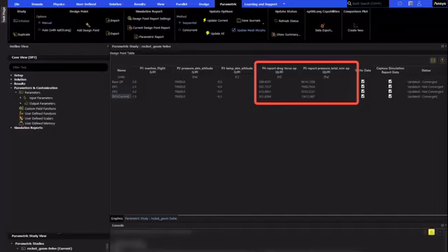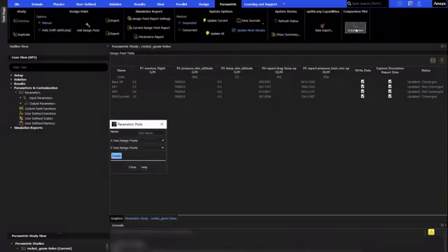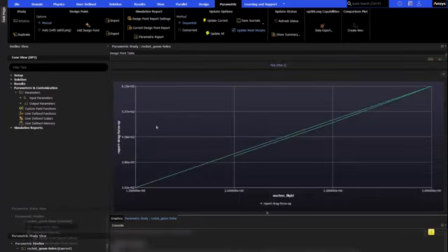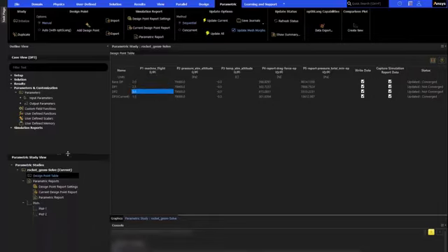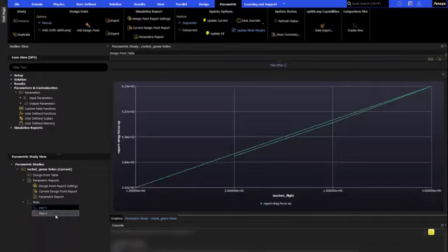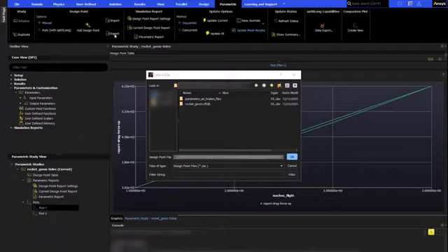To view graphically, you can also create a comparison plot for the desired variables. Here, we'll plot the Mach number against the rocket drag force. Here, we see a doubling back of the plot line because the data is plotted sequentially for the design points run. However, the design point table data can be exported into CSV format and be manipulated further outside of Fluent by selecting Export in the Design Point tab.